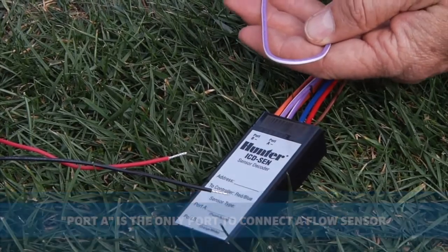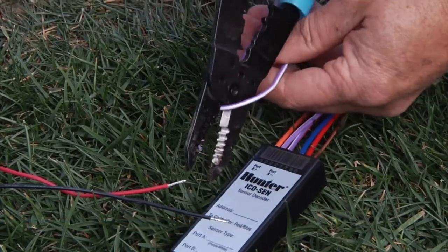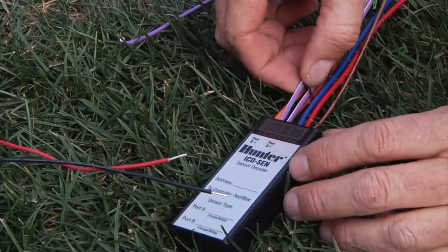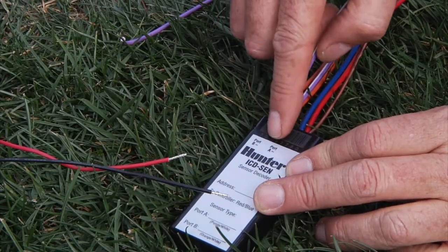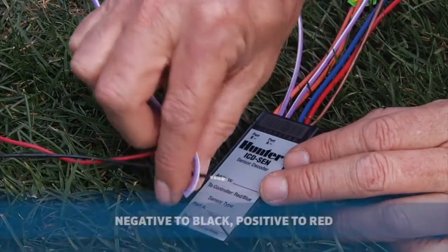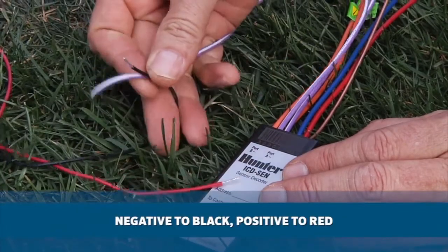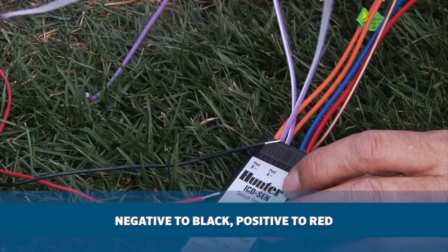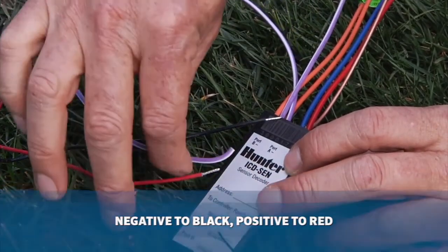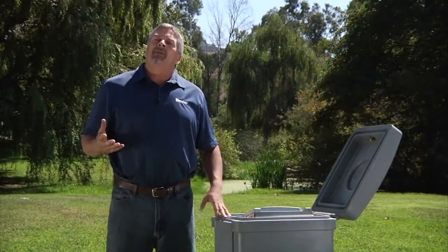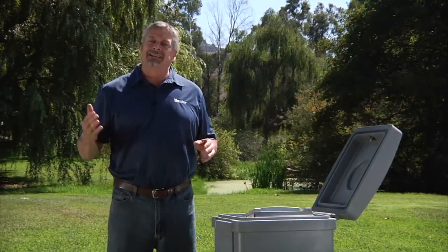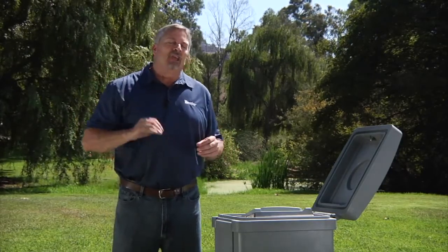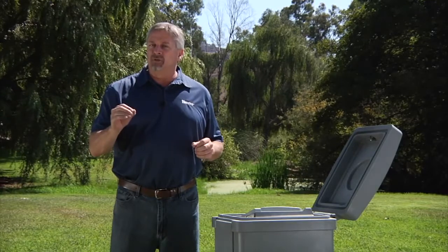When you connect a flow sensor through a sensor decoder, be sure to use the looped purple wires and that you observe polarity. As you can see, the negative side is on the front. Therefore, when you cut the looped wire, make sure to connect the black or negative wire coming from the flow sensor to the negative or front purple wire coming from the sensor decoder. Likewise, connect the red or positive wire from the sensor to the back of the positive purple wire from the decoder. So remember, whether you're hooking up your Hunter FlowSync flow sensor directly to the controller or via a decoder through the 2-wire path, you only want to utilize 1 flow sensor per controller.